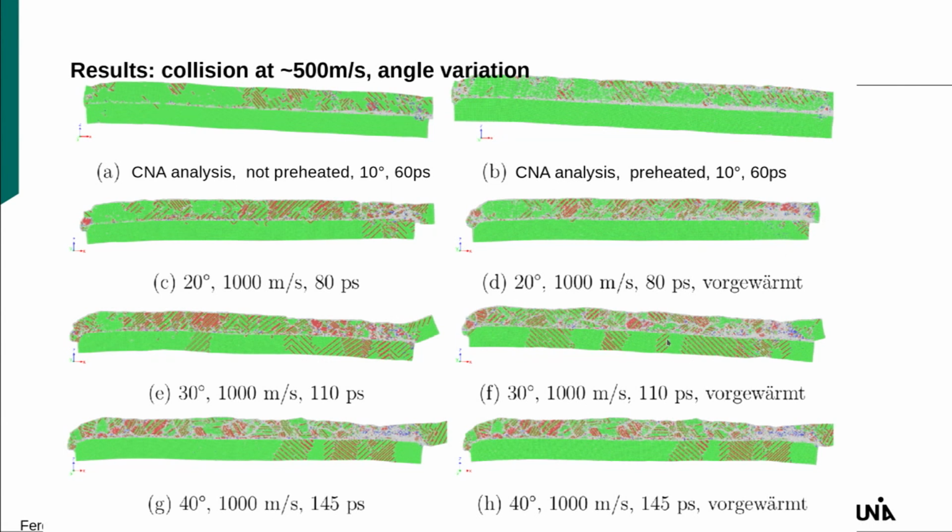So here you see also in copper, you see this high density of stacking faults, and I guess it's only because partial dislocations nucleate somewhere and they migrate outwards. Same here. But here, at least you get highly perturbed regions in the aluminum side.